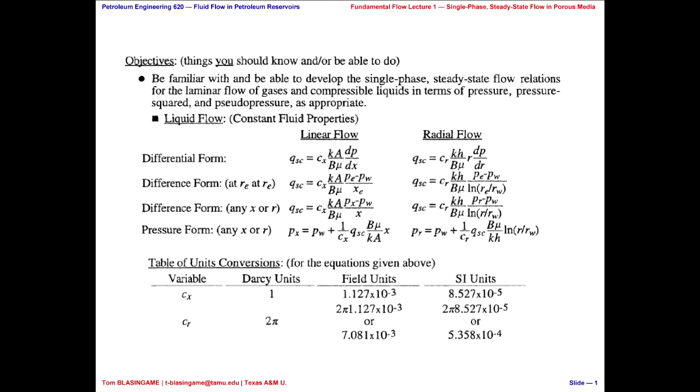Constant. What do we have to assume about formation volume factor? Well, we never talked about formation volume factor, but it is a mass-defined relationship that relates volume at the bottom of the well, or volume in the reservoir, and volume in the stock tank. We sell stock tank barrels, right? But there are reservoir barrels down there, so we have to account for their expansion. I'm explaining this because, ladies, you're always going to see everything multiplied by B. B is an expansion factor, okay?